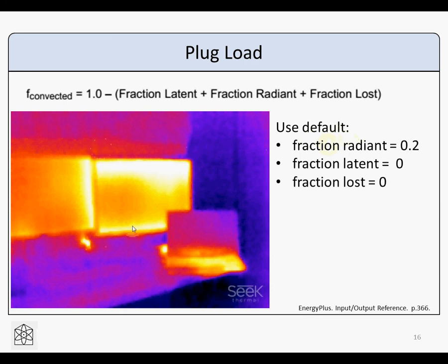And this is sort of an example of that with a thermal camera. You can see this is in the long wave spectrum. And so you can see this is the radiant energy that's coming off of, again, these computer monitors and these laptops. So that's being absorbed by surfaces and will be re-emitted in, say, 15 minutes from now.